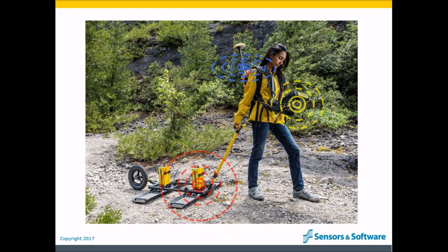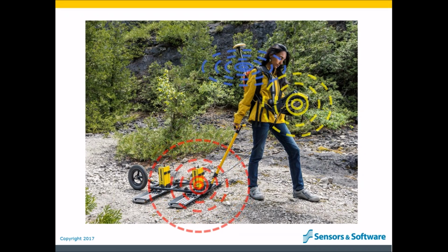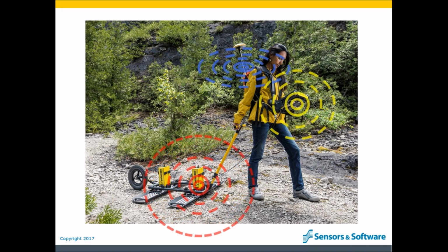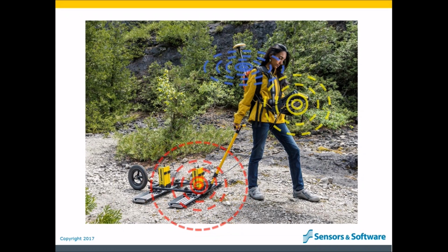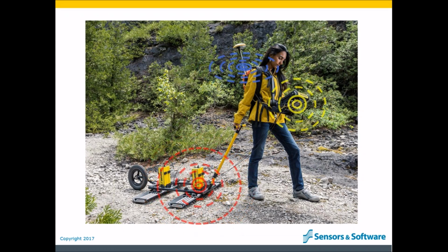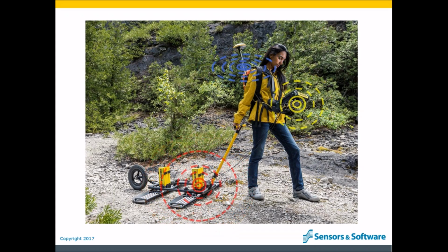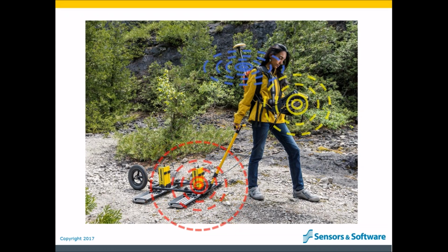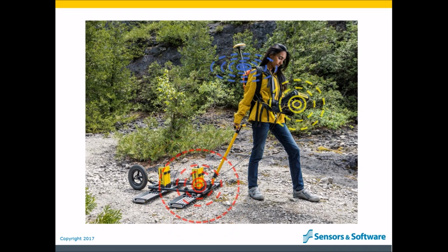It is caused by poorly placed metal cables or metal housings that get energized when the GPR transmitter fires. The energized metal becomes a second transmission source and produces spurious signals that appear in the GPR data, usually as banding. This is coherent system noise. All GPR systems, including ours, have coherent system noise. But what sets good GPR systems apart from bad GPR systems is the amount of coherent system noise that they produce. Some systems are much worse than others.